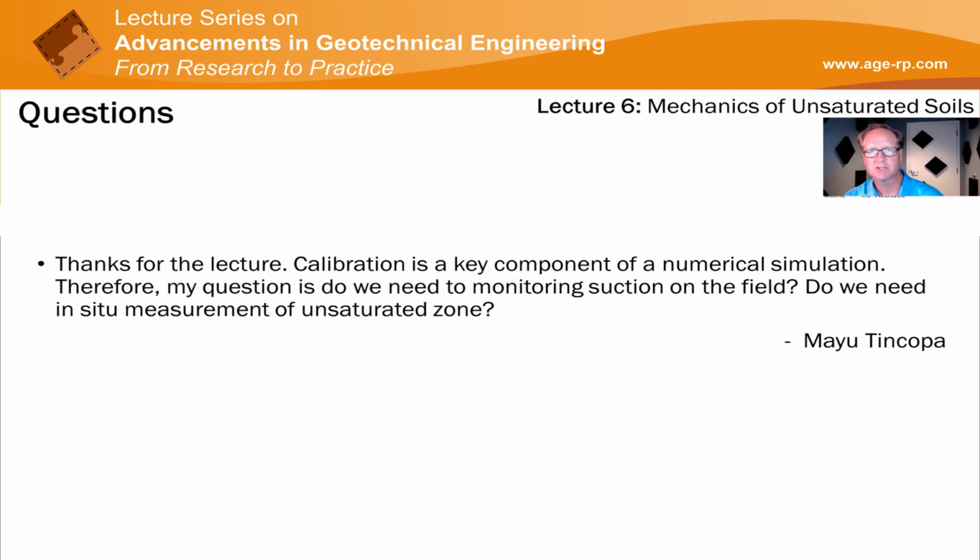So in that case, you're not even seeing your changes in soil suction. So the use of lysimeters, trying to get your net flux through into the water table, is one method. People have drilled boreholes and gone down and tried to take samples out and measure them for water contents and suctions to try to establish monitoring of suctions and water contents in the unsaturated zone.